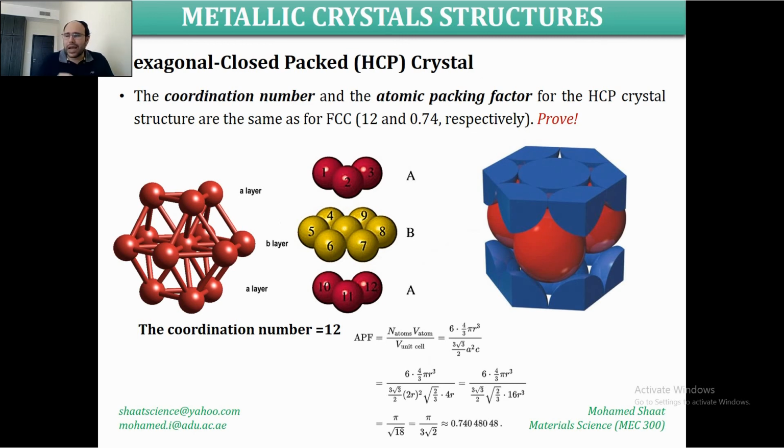In order to understand or count how many neighbors any atom belonging to this type of crystal structure has, you should consider 2 adjacent unit cells, as we have done for the FCC crystal structure. But in the BCC, we consider only 1 unit cell. We choose the core atom and count the other neighbors. This is the simplest case. But for the FCC, we had to assume 2 unit cells side by side. Here we have to do the same for the HCP.